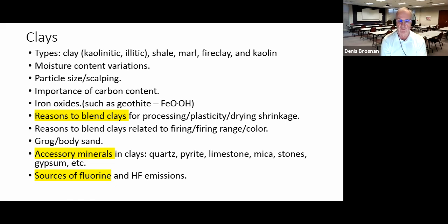The oxidized clay, the lighter colored clay is near the surface of the earth, and if you go deeper, you get into blue shale, as it's typically called, which is higher carbon content. And so that can give you problems in firing to burn that carbon out. If you don't burn it out properly, you can come into certain types of problems. Of course, we talked about iron oxides.